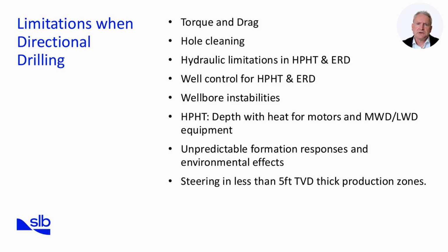3. Hydraulic limitations. As the length of the step-out extends, managing mud properties becomes challenging. 4. Well control for HPHT and ERD. Well control becomes more complex in these wells due to narrow pressure windows, delayed kick detection in long well bores, and gas migration and expansion over long distances. 5. Wellbore instabilities. Directional wells often traverse multiple formations, some of which may be unstable or reactive. This leads to problems such as borehole collapse, tight spots, or shale swelling, especially in non-inhibitive mud systems.